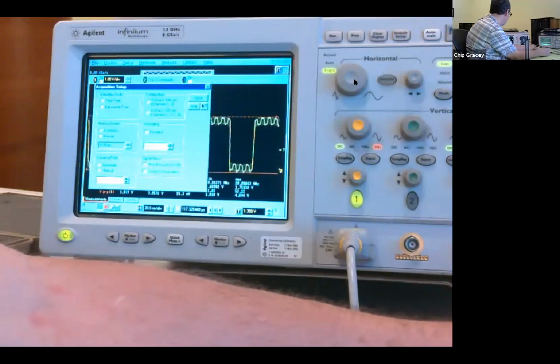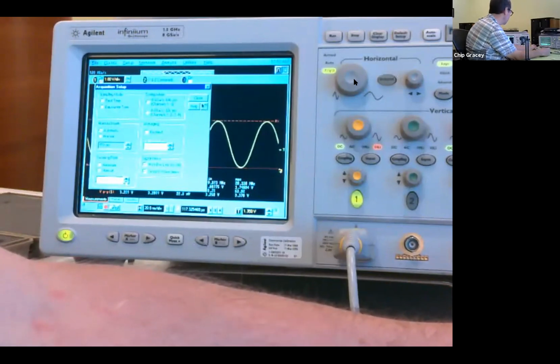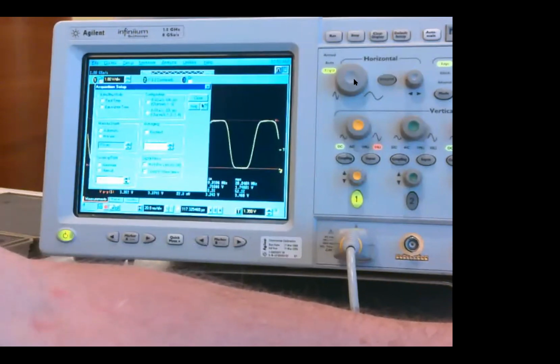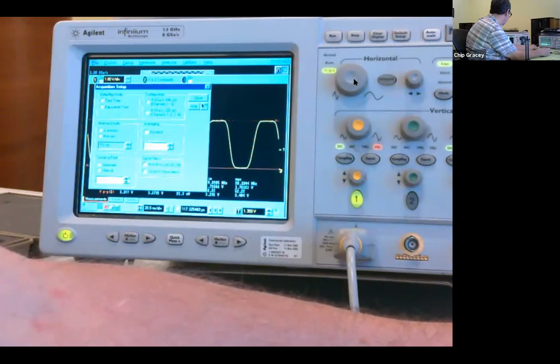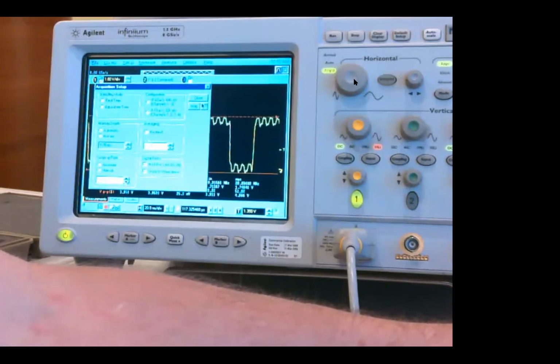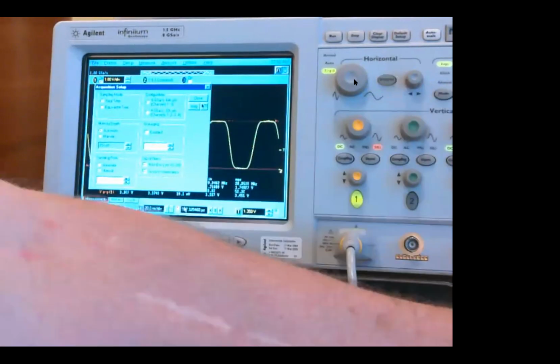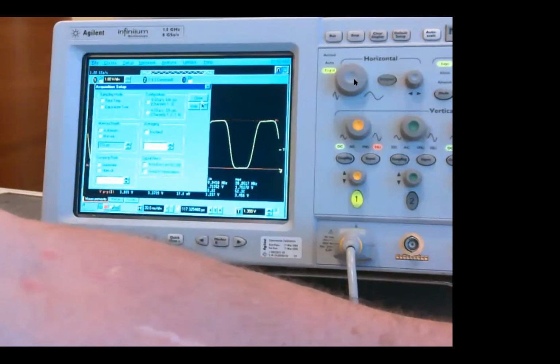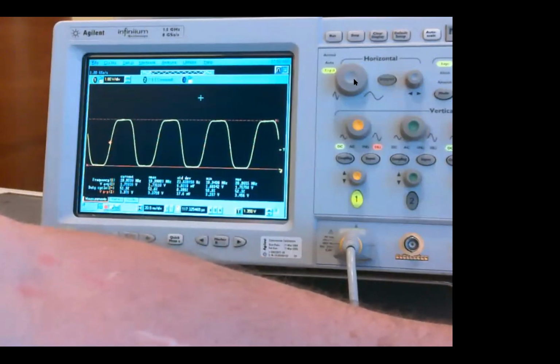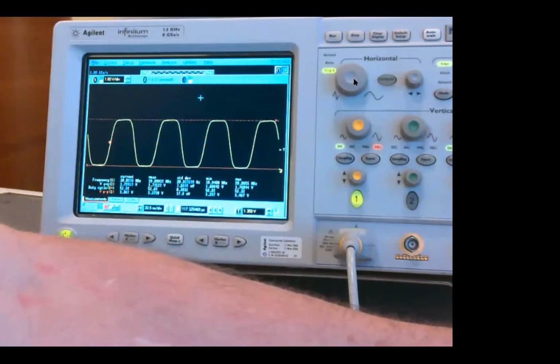So here we can see 8 gigasamples, 4, 2, and then we get down to 1. All that ringing goes away. And then here is 500 megasamples per second. It's like a sine wave. It's too low. So 1 gig is where it's clean. But as we go to 8, it really sharpens up. Yes, perfect. The apparent noise you are seeing in the high states and low states is just the harmonics. But I don't know how many lobes I'm counting.